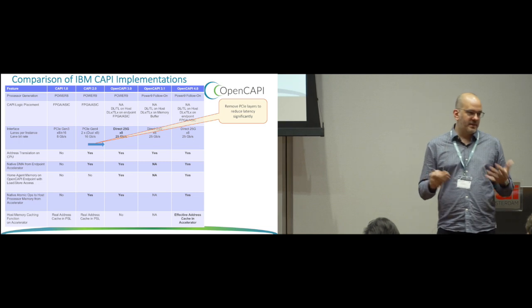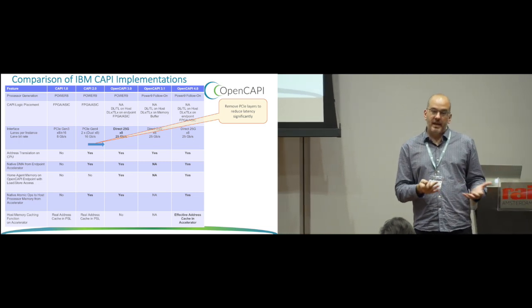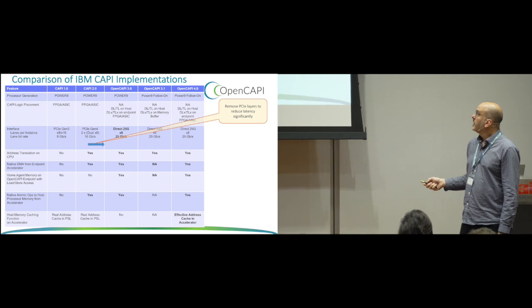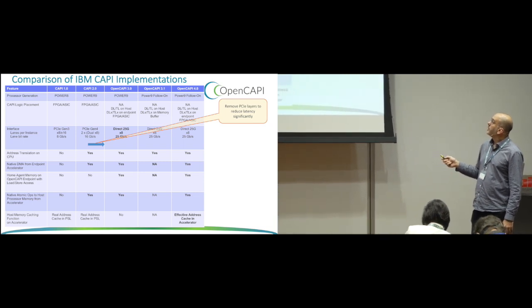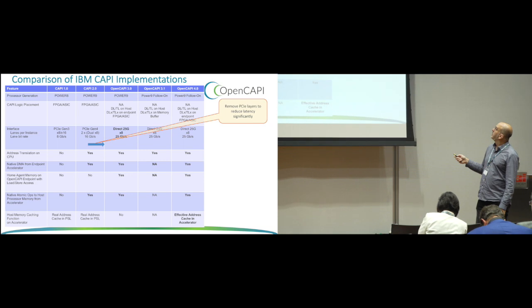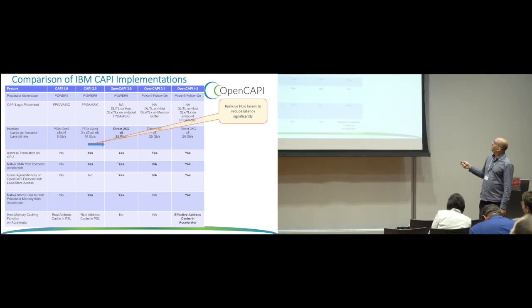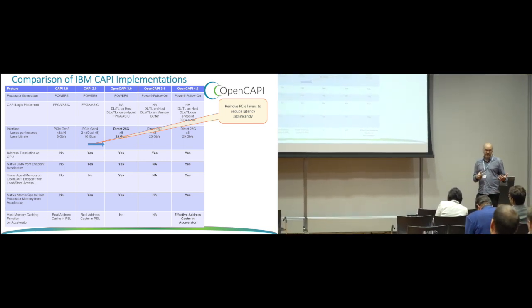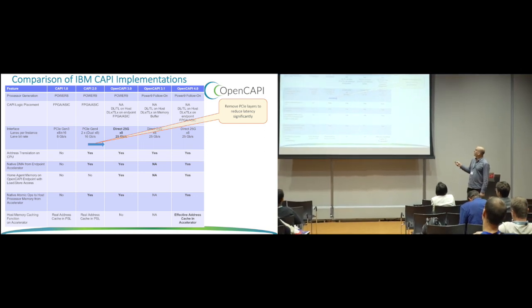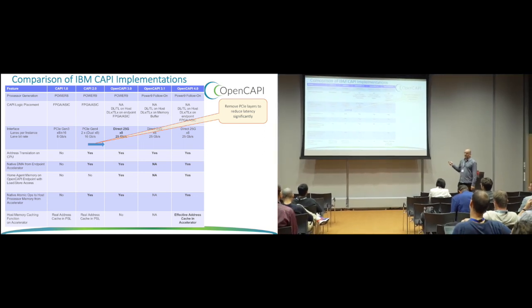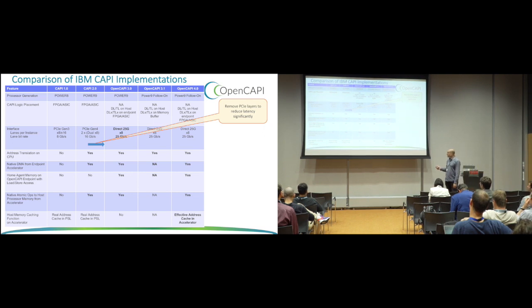We didn't have time in the schedule because we did add OpenCAPI somewhat late in the design process to Power 9. So when we go to the follow-on Power 9, our next child that we'll love, we have OpenCAPI 3.1, which is the memory interface we're talking about. And we also extended the 4.0 OpenCAPI, which contains caching capability. Now, there are some improvements, and this isn't the session on this, but the caching that was done in CAPI 1 and 2.0, we learned quite a bit from that. There's a pretty big chunk of logic on the FPGA called the PSL.